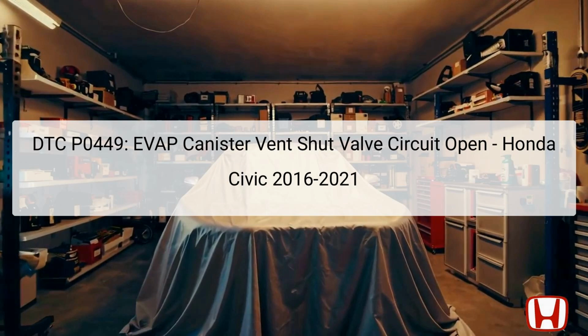The EVAP system is designed to capture fuel vapors from the fuel tank and prevent them from escaping into the atmosphere, which is crucial for both emissions control and vehicle efficiency. The EVAP canister vent shut valve is typically located near the EVAP canister, which is usually located in the rear of the vehicle, under or near the fuel tank.